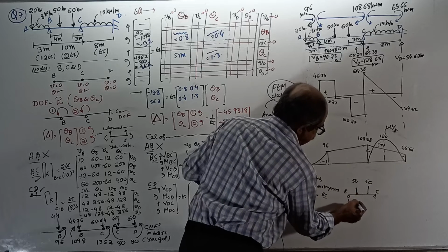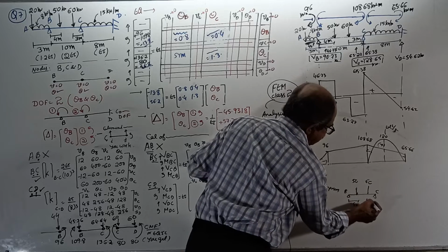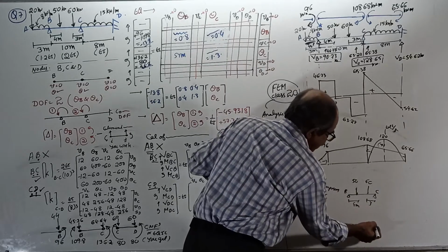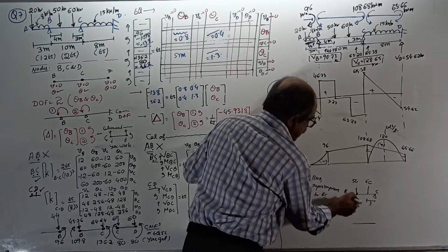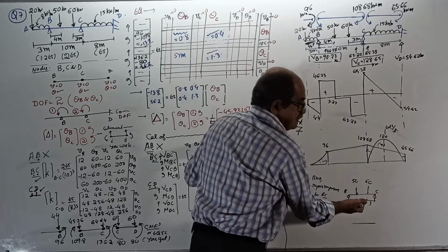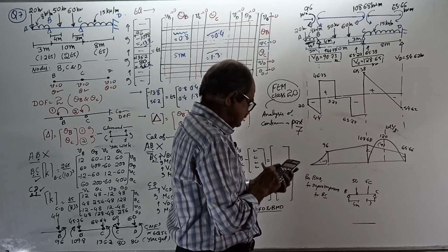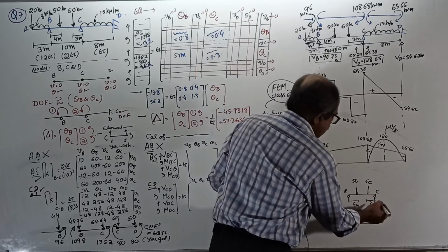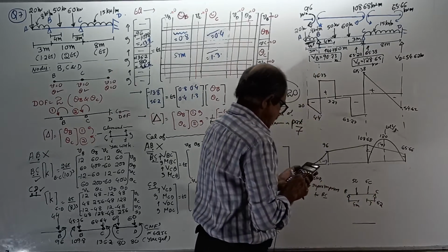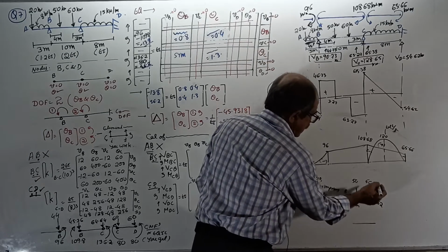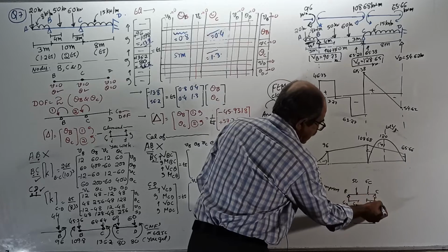See, this is 4 meter, this is 3 meter. Simply supported beam, no moment, nothing. For this one, draw BMD. How? First find reactions. Simply supported beam, if you can't find reaction, I should tell you to leave the class. That reaction will come 62. This will come 48.